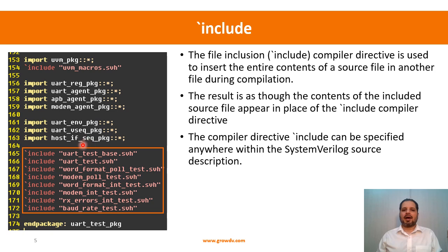This is actually a package in which the multiple files that belong to a testbench, these are all tests, are being `included in a top-level test package. So what happens is all these class definitions become part of the location where they are included. Anywhere in your SystemVerilog code, you can do `include as long as the content it brings in is legal to go in at that point. You need to ensure that, but as long as it is legal, you can do the `include.